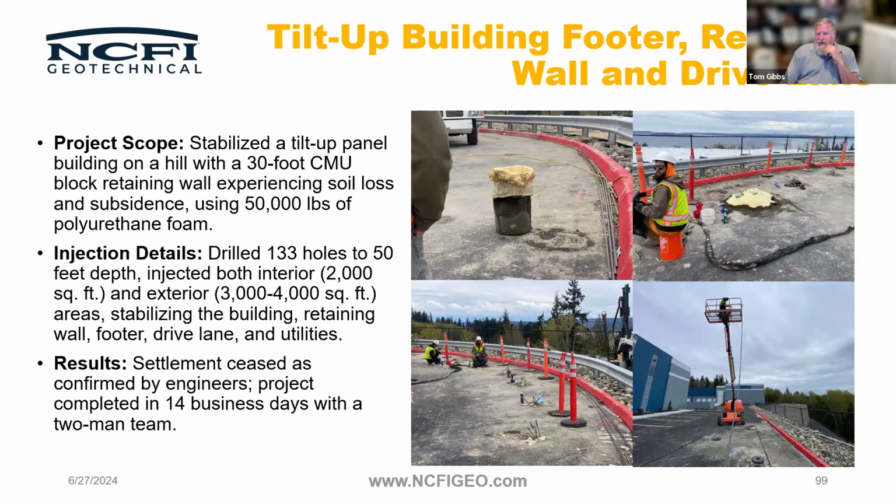But there's quite a few foundation repair contractors out there that do push piers and helical piers and micropiles and stuff. And once they've lifted a structure, they'll use the polyurethane to fill underneath the footing, fill any voids that have formed underneath the slab that's inside of the structure. It's a great fill material for those.